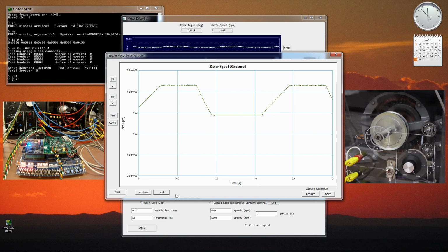So we can see the performance is, let's take a look at the smoother curve. The performance is very good again. There's no overshoot. There's a slight undershoot here. That's starting to happen already because of the fairly large delay in speed readout already at the lower speed. A higher resolution encoder would solve this problem.